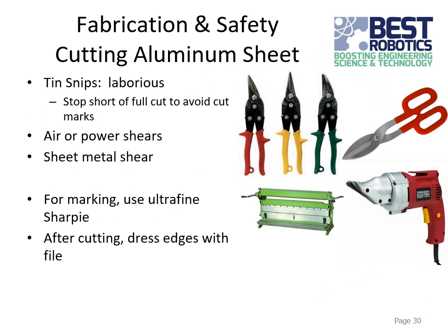For the aluminum sheet, because that's going to be like a really wide and thin sort of thing, you're probably not going to want to use those tools I just talked about for the bar and the rod. For this, you probably want to use something more like tin snips, if you have them. It can take a little bit of time to work your way through it, but it should work. It might sort of bend or deform the edges a little bit as you cut, but you can make it work.